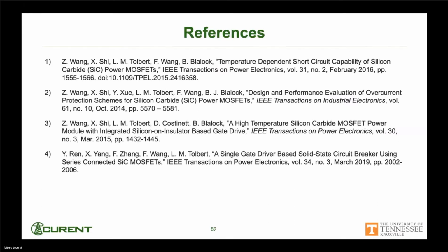Yes, we were. I think we designed it where the two rails could go anywhere from -10 to as high as 30, if I remember. We did several iterations of those. We did about 4 different integrated gate driver chips, and we kept trying to push up the amount of current that we could drive.